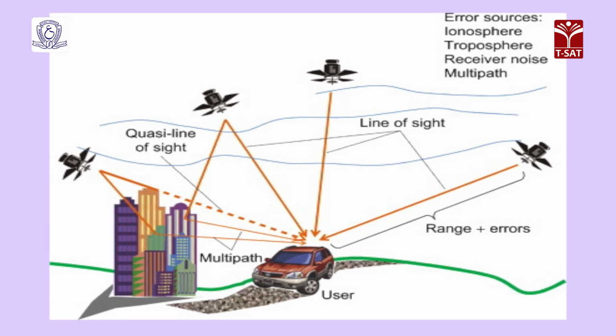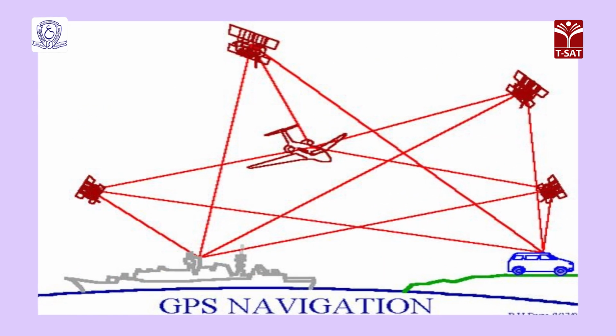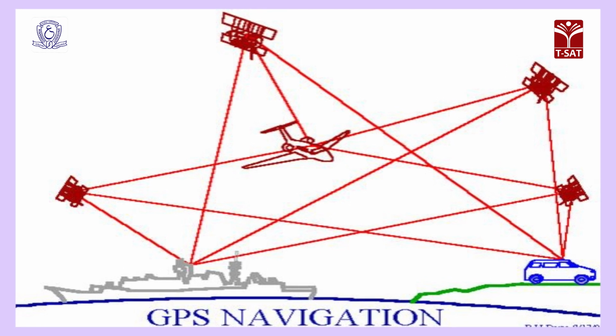Master stations collect the data about the satellites of this system continuously from the other tracking stations. The master control segment processes the tracking data for computation of satellite ephemerides, or coordinates, and satellite clock parameters. The master control station uploads ephemeris and clock data to the satellite vehicles. The satellite vehicles then send a subset of the orbital ephemeris data to the GPS receiver over radio signals.